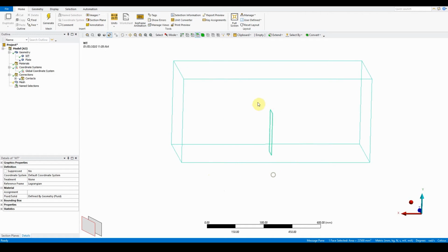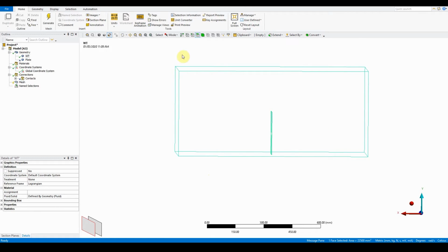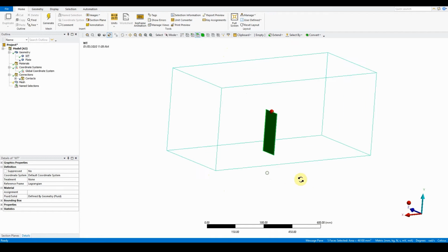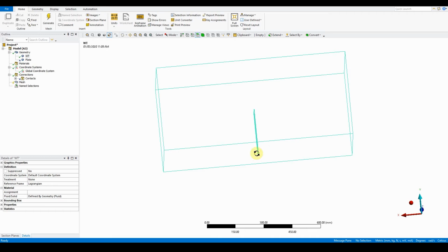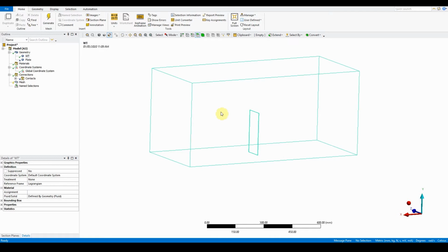Okay, now obviously there's quite a few faces here. You can individually grab them, but what I want to show you is the box tool selection. So again, in the mode up here, you've got box select, and you can select a box and it'll grab all of those. Obviously now to go back, you have to go back to single select, otherwise it will always be box select. Now there is a quick shortcut for this. I'll try my best to explain. On your mouse, if you hold down the right mouse button, you'll see the plus sign come up, and then whilst holding the right mouse button, left click as well, and you'll see it toggles through the box select and single select, which is a unique way of doing it much quicker.